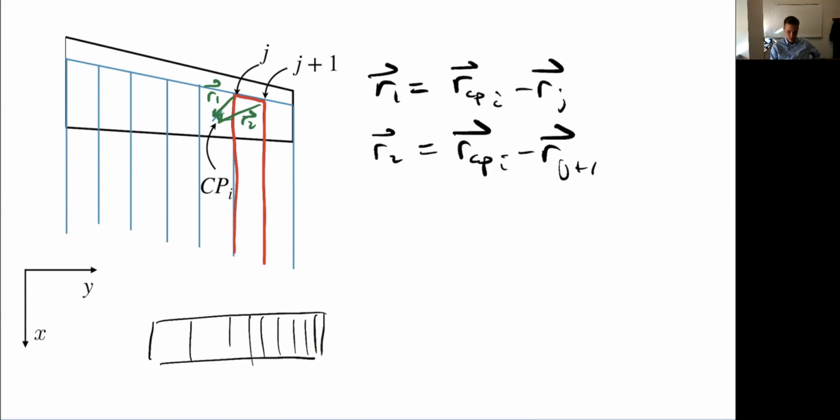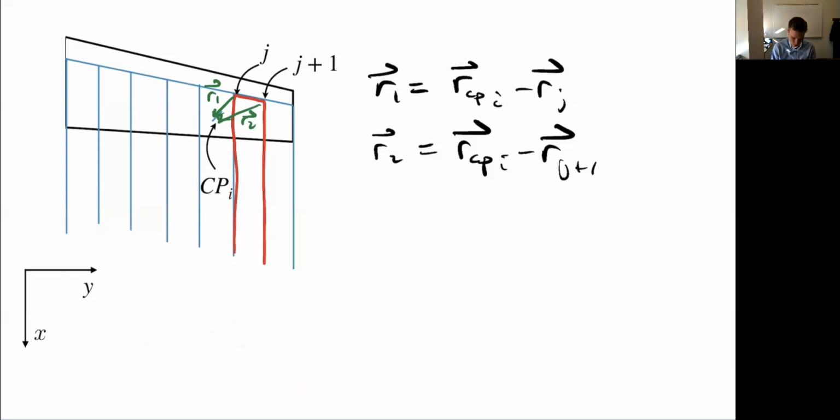towards the tip, right? So my horseshoe vortices will be bigger at the root, and then they're going to progressively get smaller and smaller and be much smaller at the tip. And I do that because my lift distribution, remember, is changing much more rapidly at the tip. So if I was again to draw the side view here, like something like this, where this is gamma and this is y, and it's fairly flat inboard and then changes rapidly towards the tip. So I may want more panels towards the tip.